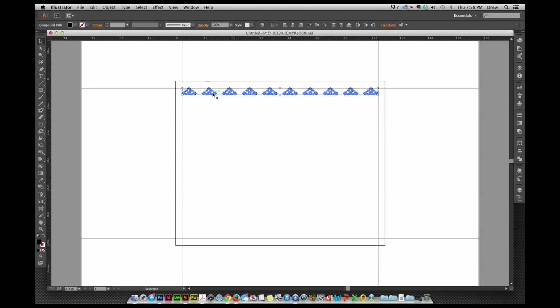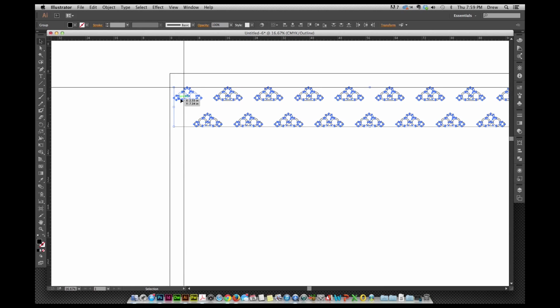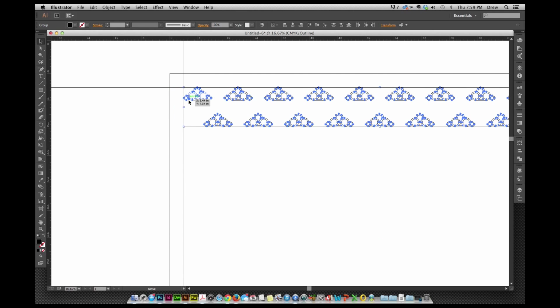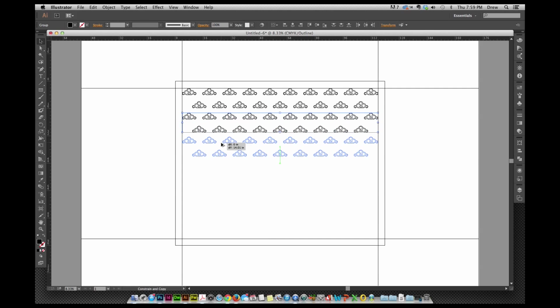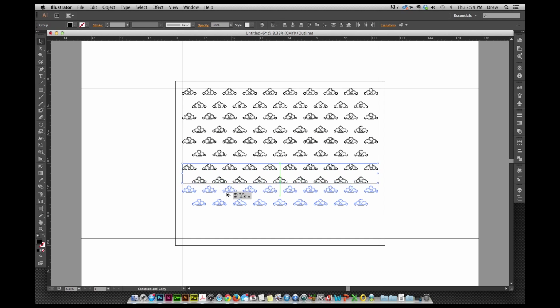Alright, I'll drag a second line down here. Let's get rid of one of these so they'll offset. And I'm going to group these two together by rows. Alright. Center these guys on each other. Snap this back to the guide. And I'm working in outline mode here just because I can see the vector real quick. This will produce a nice small file size when you send it to your printer. They'll be happy. It's going to load with no problem.